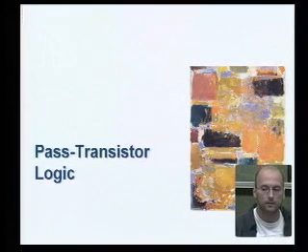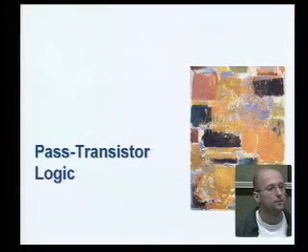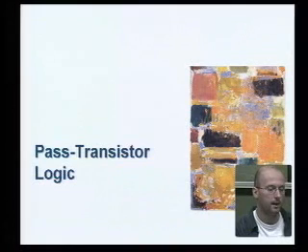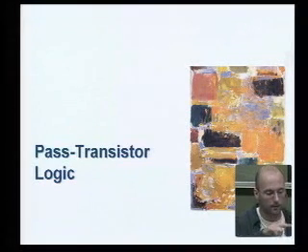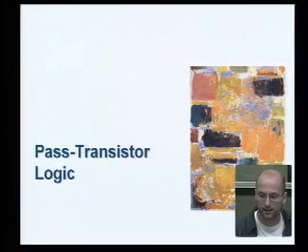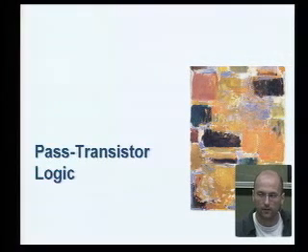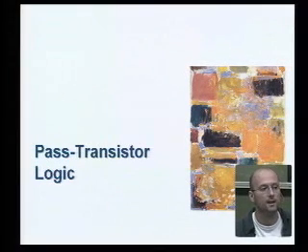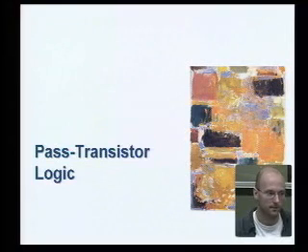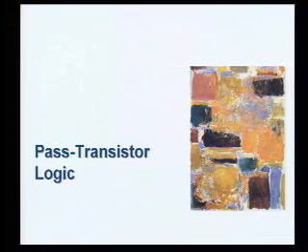Over here, you assume that your previous gates are also implemented in this CVSL. And they also have this kind of feedback mechanism, and then you assume that you have true and complementary outputs going in opposite directions at the same time. But that is actually a very good introduction for pass transistor logic, that we will see is another way of implementing these functions using complementary signals, and we will see how they become available. But we assume that they come from the same type of logic gate.